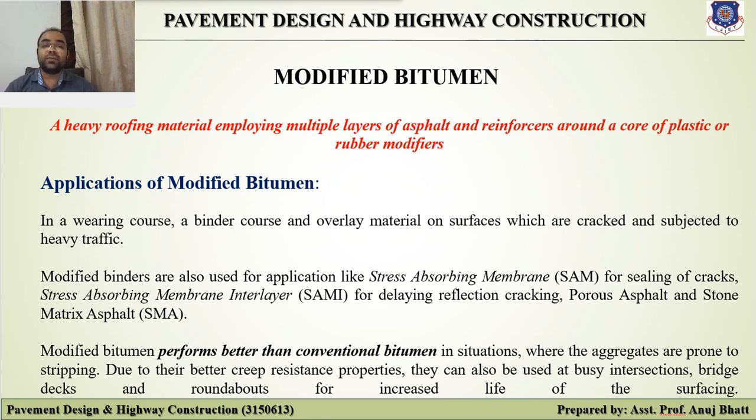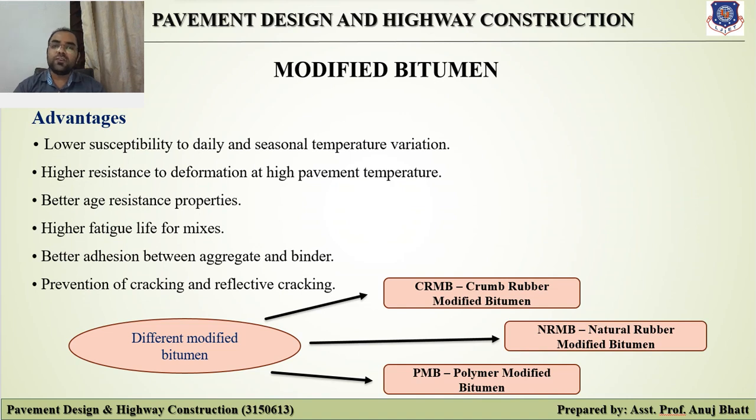There are a few advantages of modified bitumens. It has lower susceptibility to daily and seasonal temperature variation. It also has high resistance to deformation at high pavement temperature. They have better age resistance properties. They have higher fatigue life for mixes. Also, better adhesion between aggregate and binder.